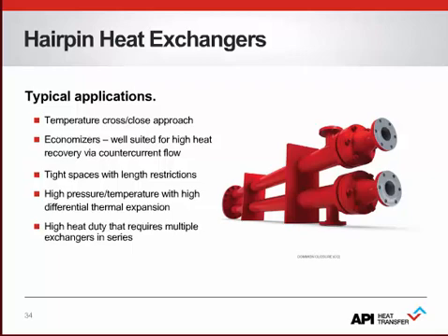The U-bend design allows independent movement for thermal expansion in high temperature differential environments, which again lends itself well to a hairpin design. Where a traditional U-tube may not be a good solution for this due to a temperature cross or a temperature differential across the tube sheet, the hairpin offers true countercurrent design and thermally separated tube sheets. As previously discussed, the hairpin is also a better option when multiple long TEMA types would be required in series.